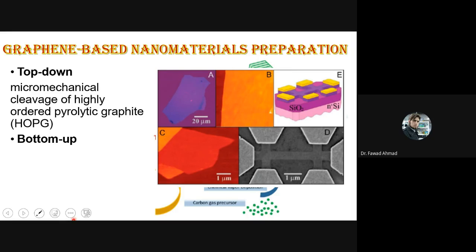First, they take the graphite and oxidize it with various oxygen functionalities, which are hydroxy group, epoxy group, alkoxy group, or carboxy or carbonyl group. In the second stage, that graphite oxide is exfoliated by ultrasonication, or by mechanical treatment, or by any chemical treatment, or by any thermal treatment to produce graphene oxide.